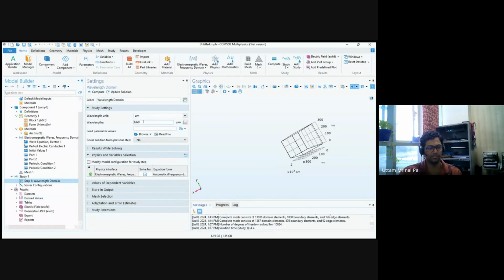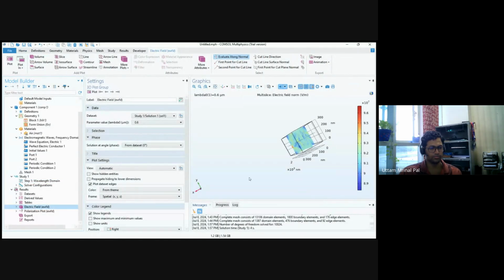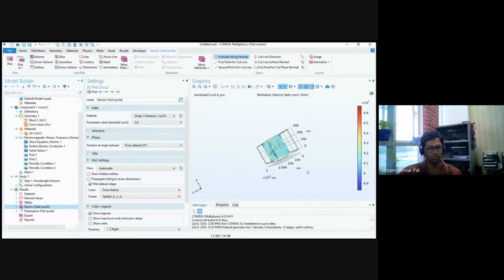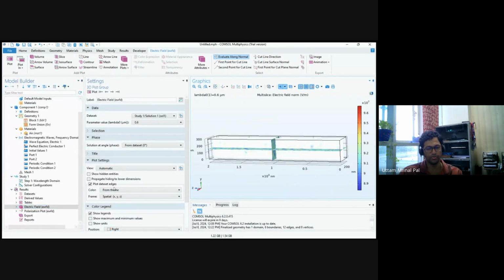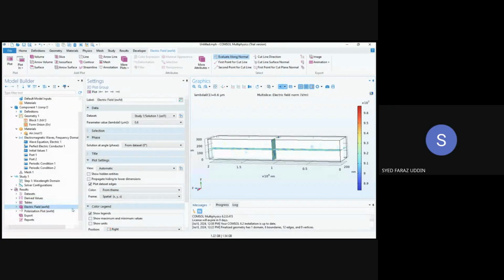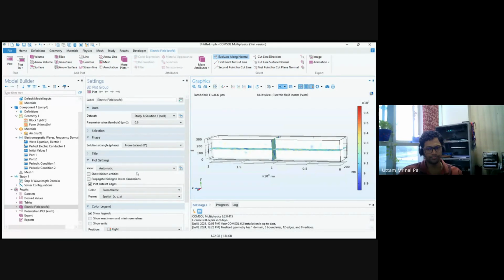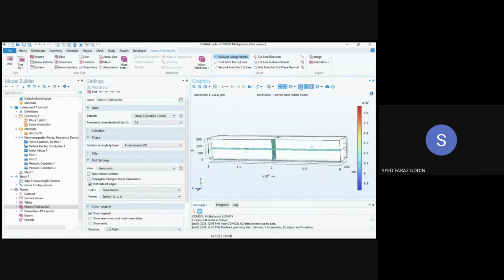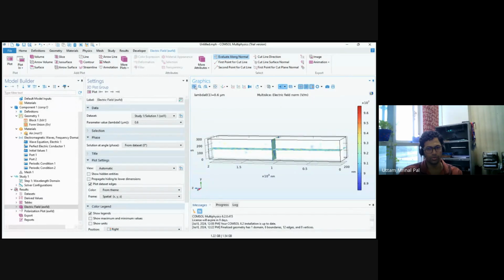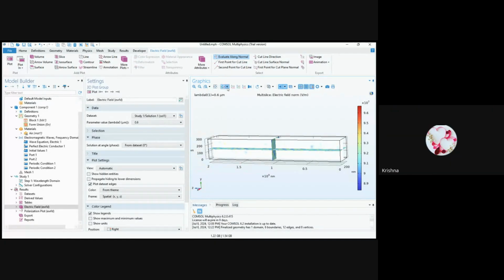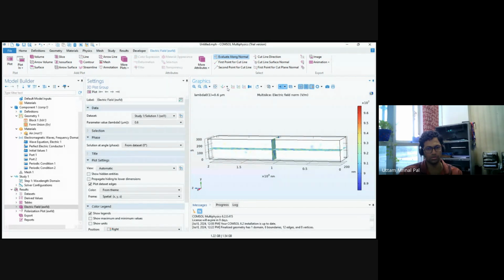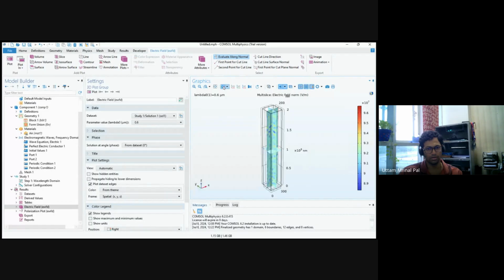Now you can change this in multi slice. You open the electric field plot and then change the multi slice parameter that you are plotting, and you go to the reset 3D view. In the graphics pane, it's the fifth button from the top left side. Left click on that, not on the arrow, just on the left. That one. Left click. Good.